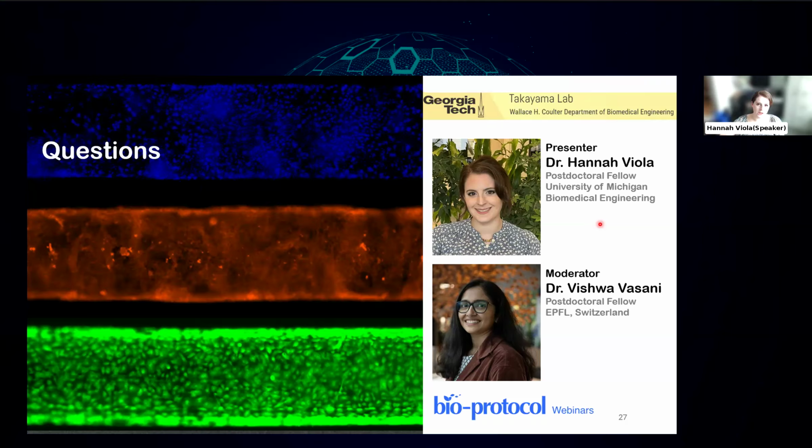But if you're seeing high surface roughness, one of the causes could be that you're clogging chips into the tool, which is compromising the tool's ability to cut. That could be because there's too much heat, so you might want to take down your spindle speed and your feed rate, because you could be generating a lot of heat. Another way to tell is to physically look at the tool while the cut is happening. You can sometimes pause in the middle of your protocol and see if the tool is full of plastic. So that's one downside of cutting plastics. They don't have a low melting temperature, but they do melt easier than something like metal. So it's something you've got to be aware of.